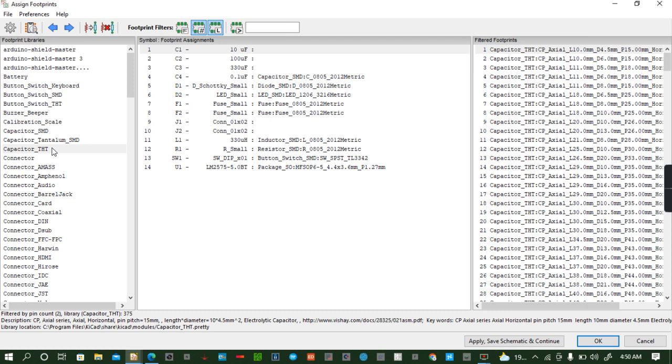But again, it is very advantageous because you will have a strong joint as compared to SMD. So when you are doing an SMD design, it cannot be purely SMD. You have to mix because some things that require a lot of power, like the pin socket connectors, should be through hole for them to give us a strong joint that we deserve.